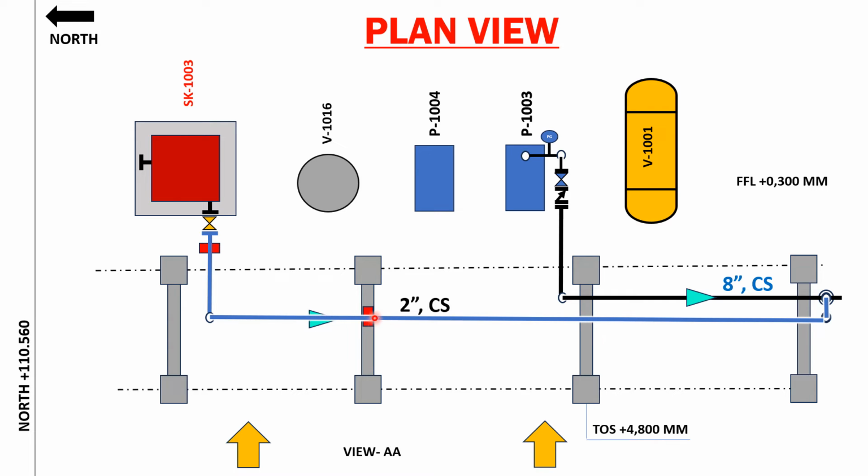So next support we are placing it over here. This is actually a natural support. Here you have a pipe rack. So instead of placing the line directly on the pipe rack, you have to put some support over here. These supports are generally shoe supports, because when you're placing a pipe directly over the pipe rack, if